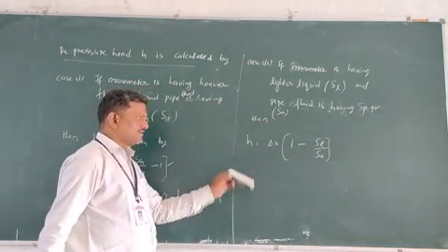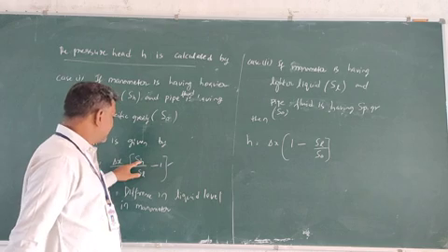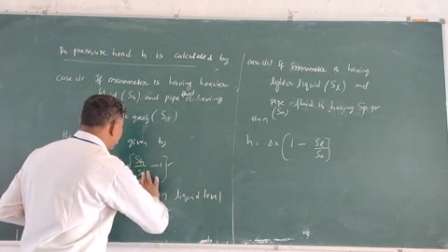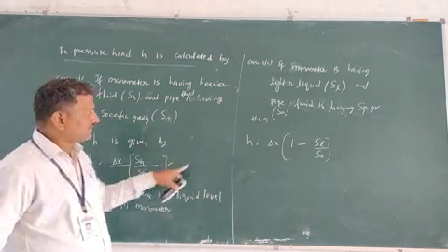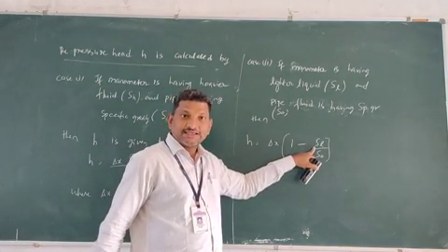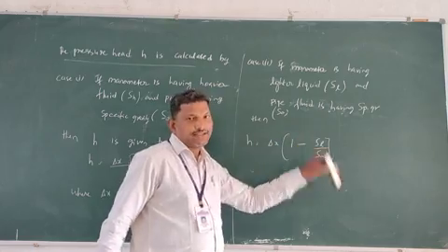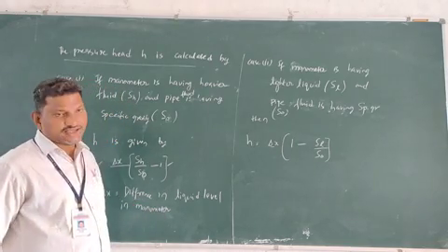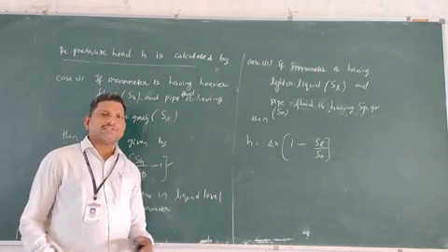Then we can use this. SH is the heavier fluid specific gravity, S0 is the pipe fluid specific gravity, SL is the specific gravity of the light liquid. Delta X is the same, the difference in the liquid level in the manometer.